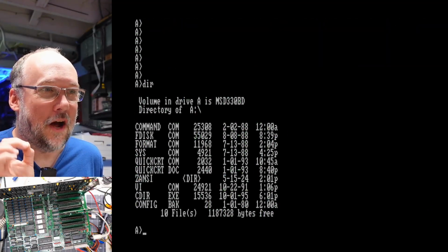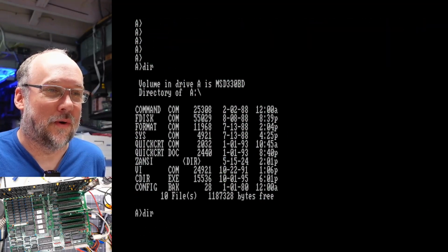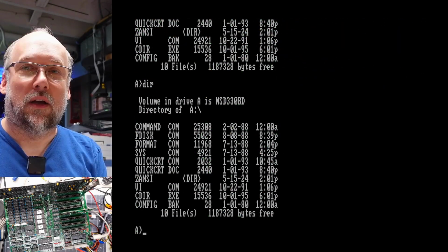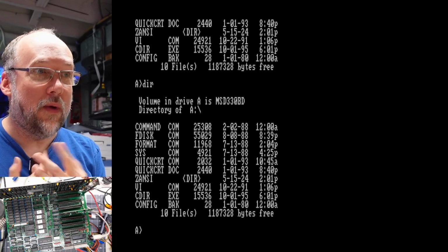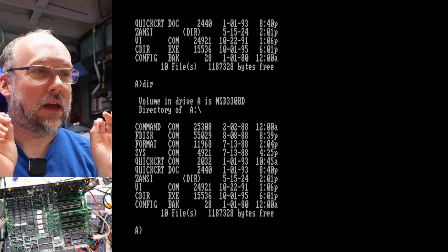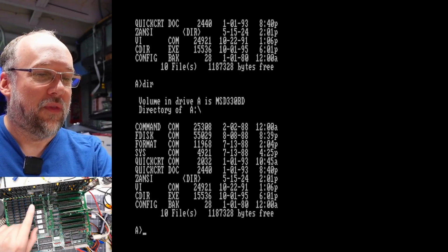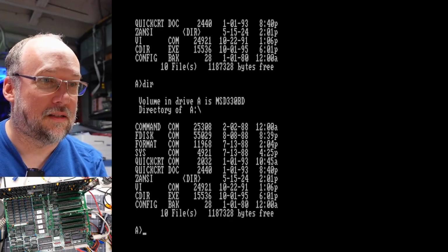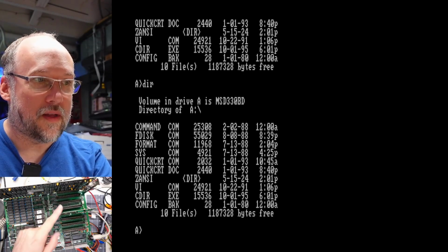Now, this doesn't speed up anything whatsoever, right? Because of course, DOS is still waiting for that vertical refresh and stuff to happen. You know what? I just had a thought. We might be able to do another trick here to trick the system into always thinking it's in vertical refresh. That signal that I cut here, and when we unplugged the wire, you know, we weren't getting any screen updates. Well, let's go figure out where that signal goes.